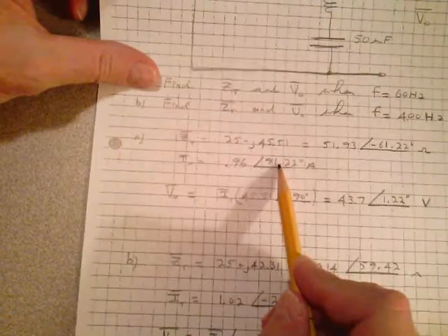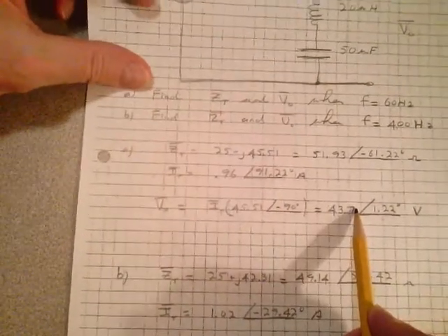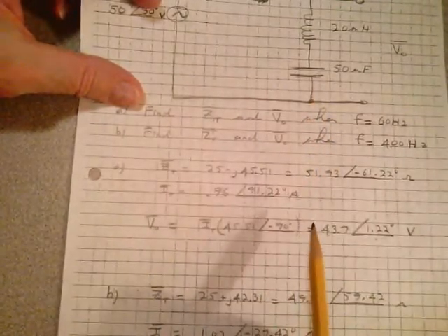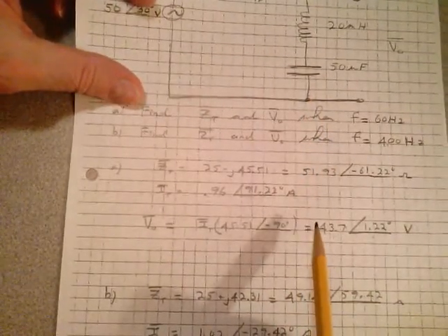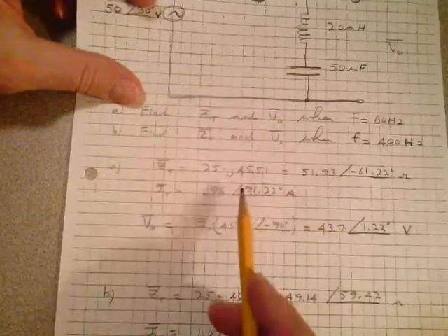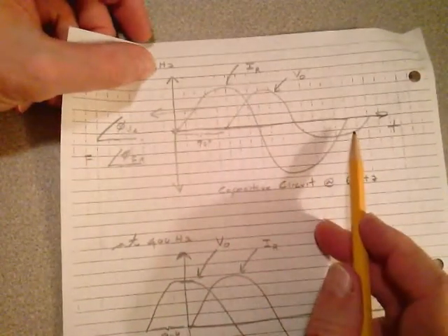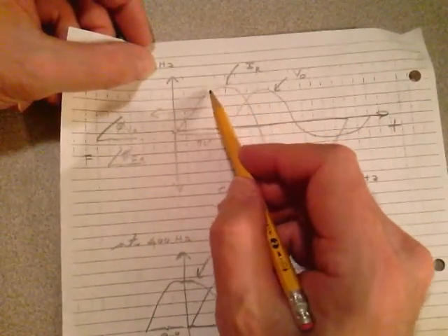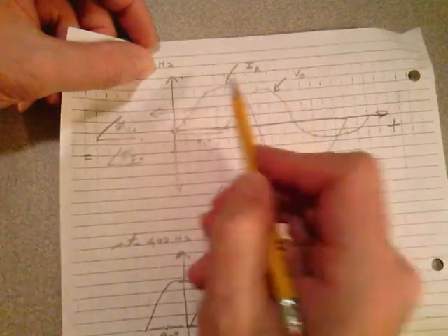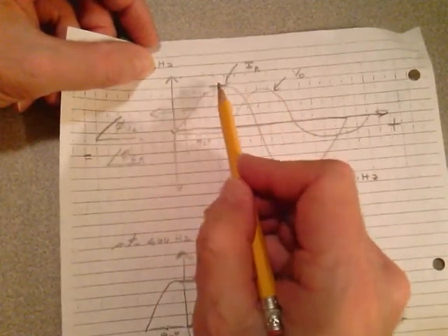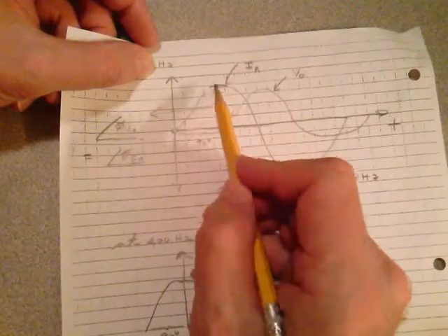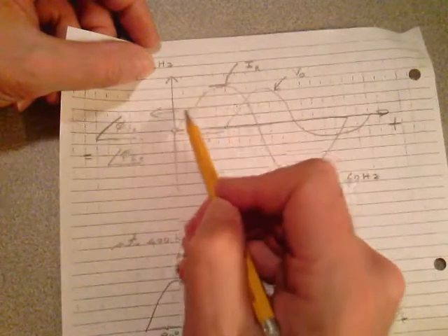You would expect the current to lead the voltage by 90 degrees at 60 hertz in part A because it looks like a capacitive circuit, and voltage can't change instantaneously across the capacitor, so the current has to lead the voltage. That's what you would see on an oscilloscope if we built this in lab. Don't forget, this current is really the voltage across the resistor. We're just interested in the waveform, not the magnitude, but it's the same phase as the current through the resistor.